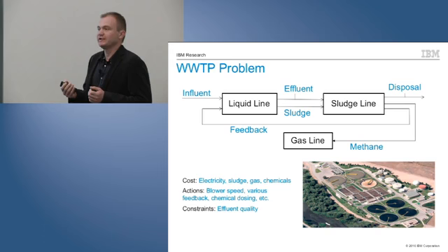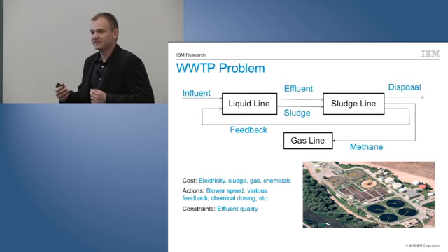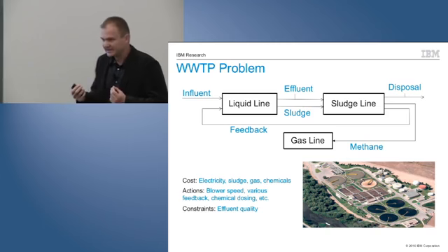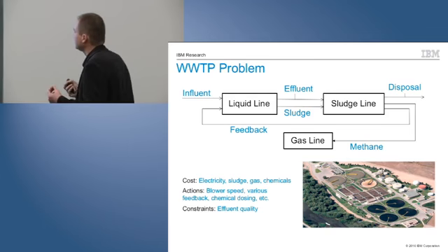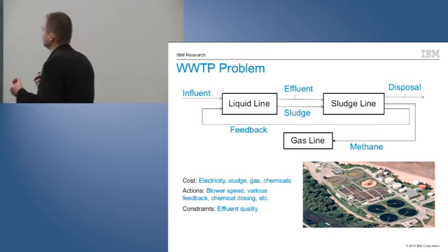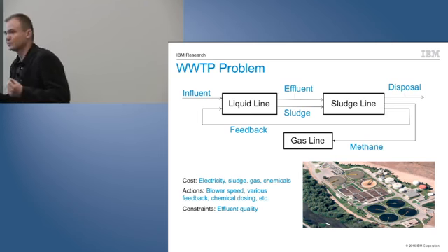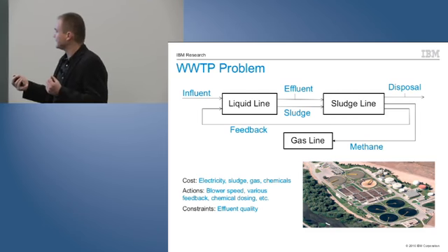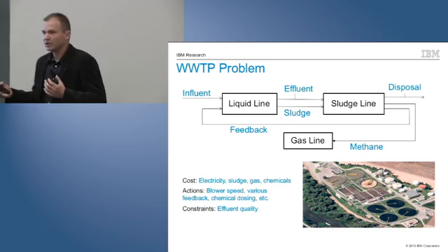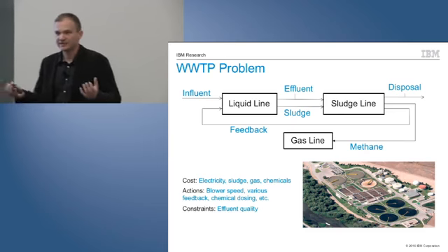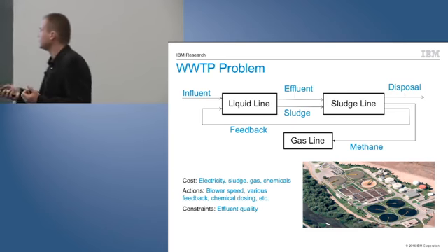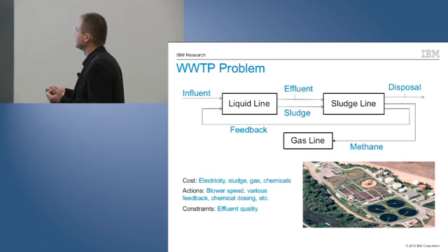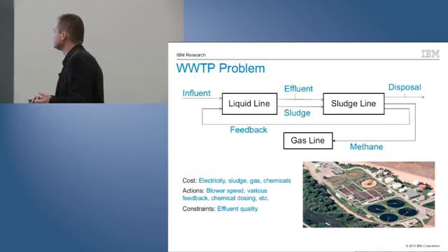Biological treatment is actually done by the bacteria that is coming with the sewage. The activity of these bacteria is determined by the concentration of dissolved oxygen in the reactor, and this is determined by the big blowers at the bottom of the reactor. In addition, to treat certain chemicals such as phosphorus, chemical reagents are added to the water as well.